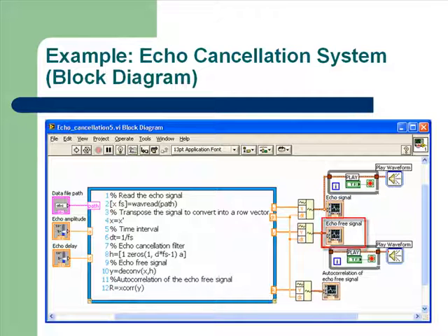An echo-free signal is attempted to be recovered from the echo signal by performing deconvolution with an echo cancellation filter that is based on the echo amplitude and echo delay inputs. The echo signal and what we hope to be an echo-free signal are displayed to the user and played through the computer's speakers when the corresponding play buttons are pressed. The autocorrelation of the echo-free signal is also displayed for a visual representation of how successful the echo cancellation was.